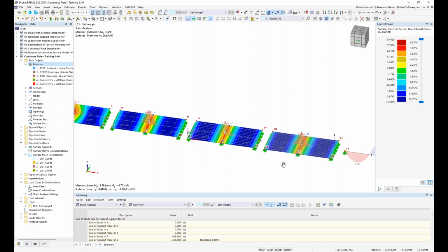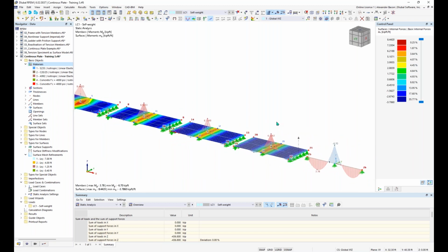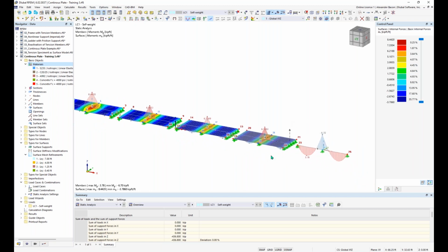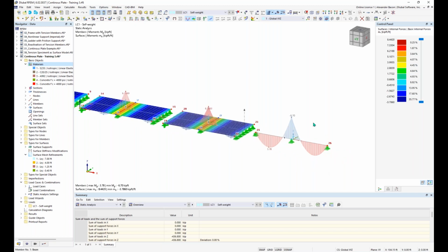And yeah, so in RFEM, we can now talk about shear stiffness. With shear stiffness, when it comes to hand calculations, if you're trying to, let's say, for example, do hand calculations to match the results of the beam here, you have to take into account shear stiffness effects. So taking into account shear stiffness, this is what RFEM does in the program.